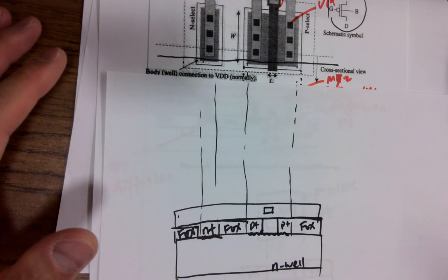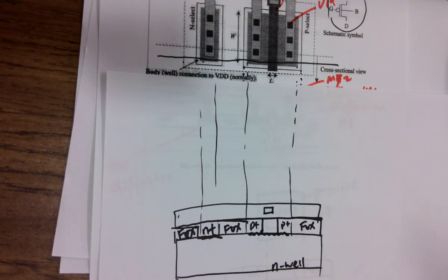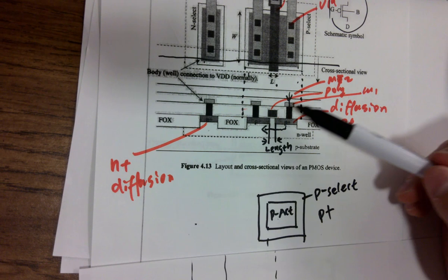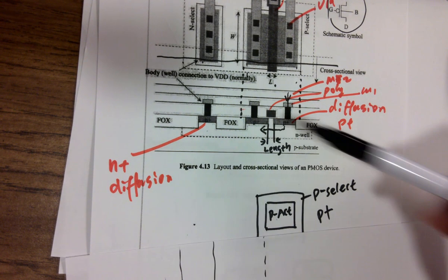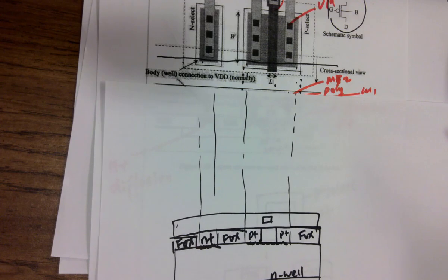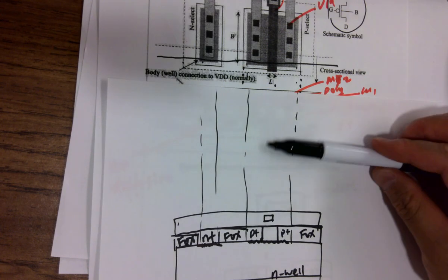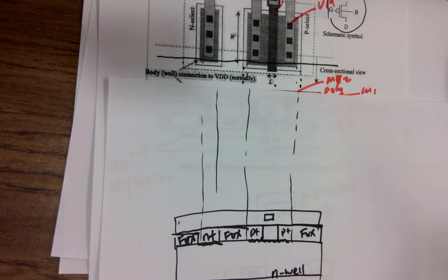There's no metal, no via. Right? So the difference between this one and the one here is that this one crosses the vias and metal one. So you have to draw the vias and metal one here. But for this one, it skips it. It's on the side. In between, like where the P plus and Fox layer, and then up to M1 where the vias are drawn on the first diagram, is everything besides the via and the poly just an insulator?